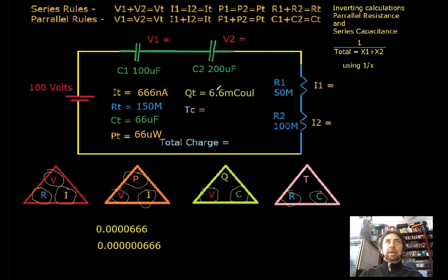So now what we have is we've completed this particular part of the arrangement where we've got the total amount of charge. That comes in very, very handy when we want to calculate the total voltage drop and total current moving forward. But let's complete this particular calculation by calculating the tau, or time constant for this circuit, which is resistance multiplied by the total amount of capacitance.